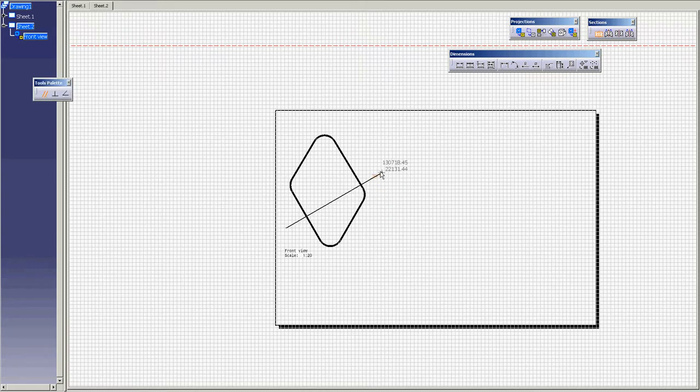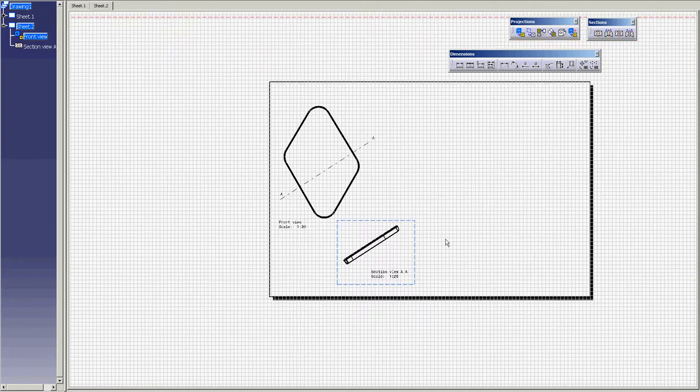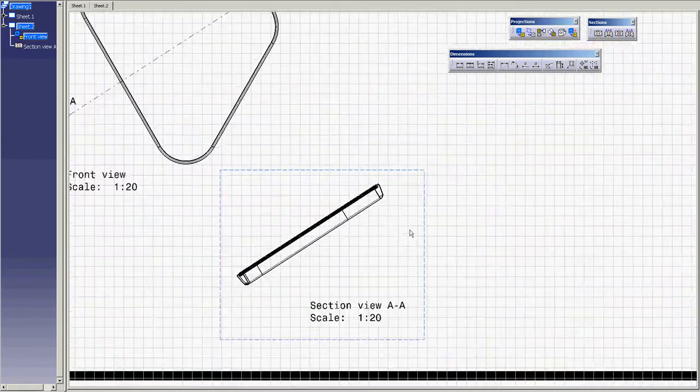And what we want to do is double click when you're ready. When you double click, it's going to let you pull that section off and place it where you want to put it on the page. Click OK. It looks good. So there's our section.